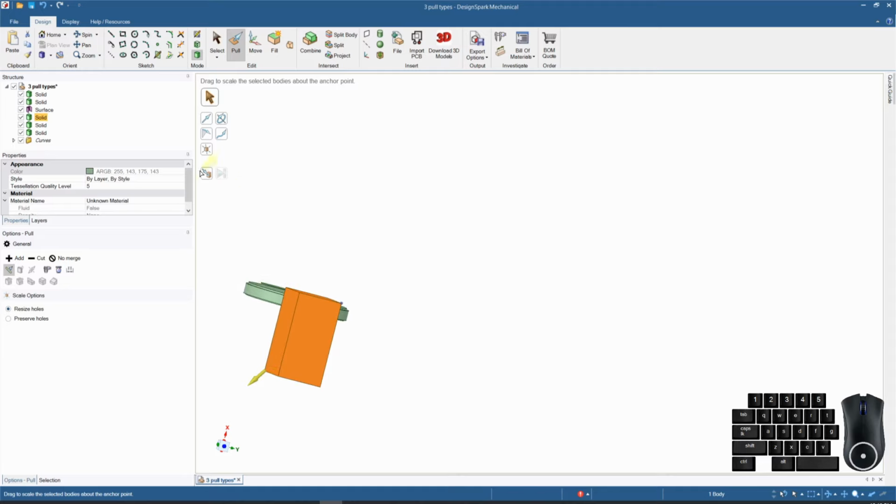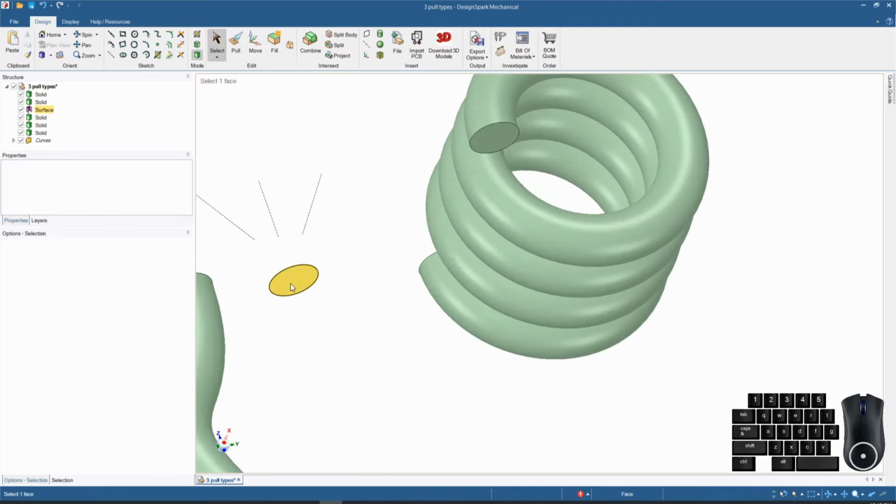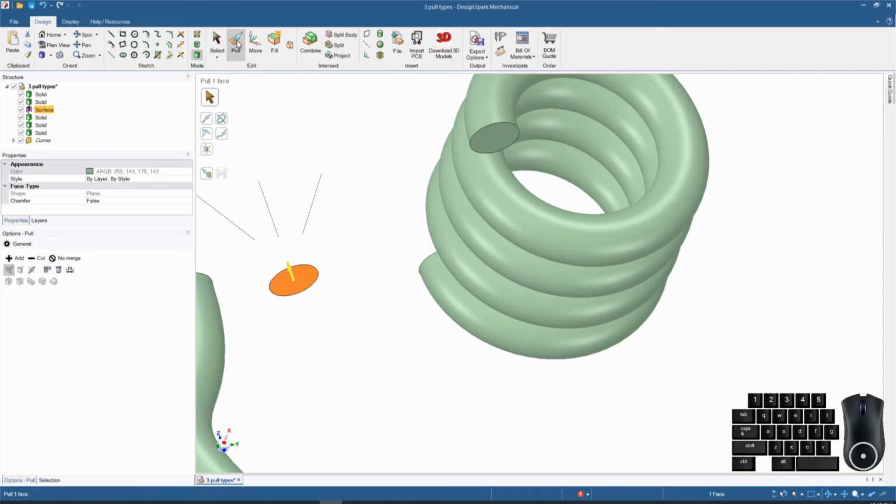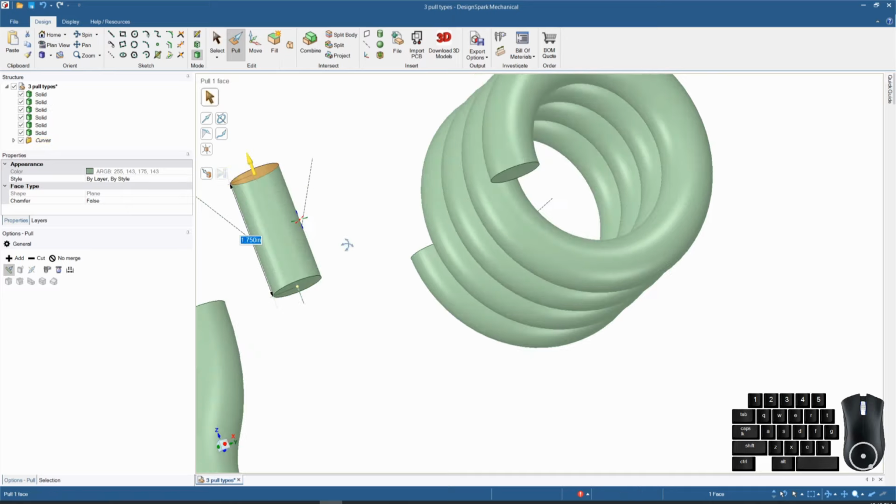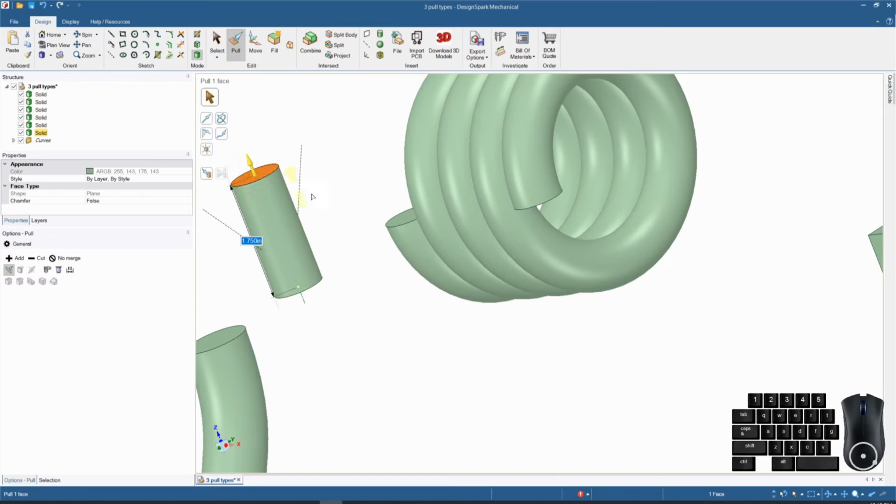And I guess there's one more that we kind of forgot, and that's the up to tool. So when you're pulling surfaces, let me show you that really quick. If I just do a standard simple pull, you can tell it to pull in the direction of the arrow up to a point, and that's easy enough to do by doing the up to and then finding a point to pull it to, and it will pull that surface up to that location. Really similar to the Move tool.